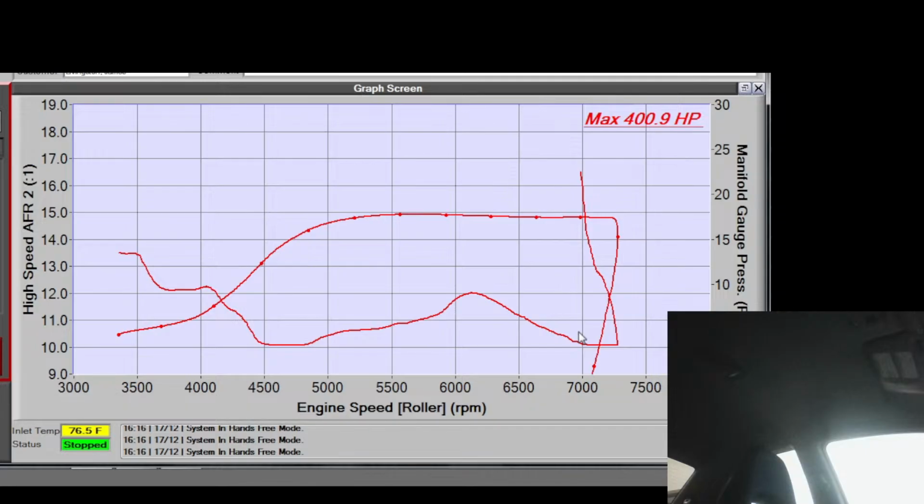Don's maps: the car has a fueling issue and a boost control issue, at 16 psi at 0% base wastegate duty cycle versus the 9 psi that it should. It reads 255 grams of air, making it run very rich. Cleaning the map made no change. The boost control line sounds okay, but potentially the solenoid is bad.